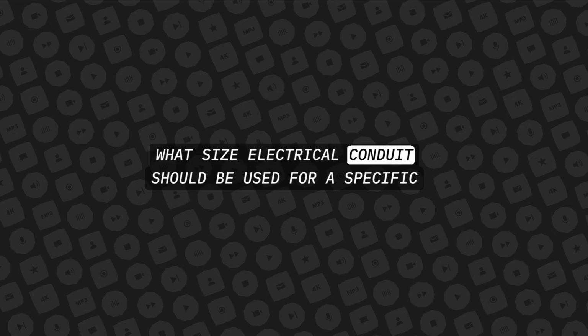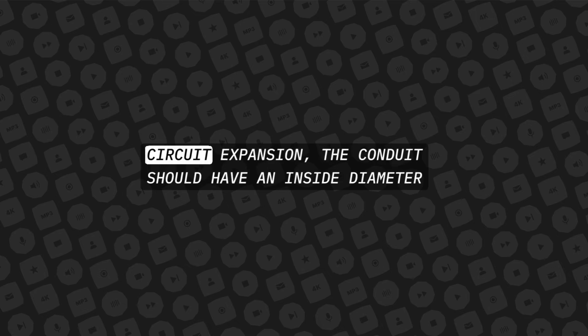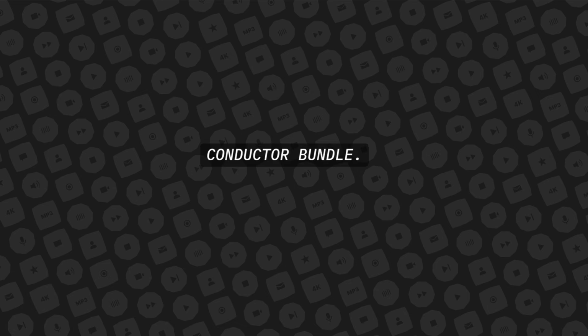What size electrical conduit should be used for a specific cable bundle? To allow for ease of maintenance and possible future circuit expansion, the conduit should have an inside diameter that is 25% larger than the maximum diameter of the conductor bundle.